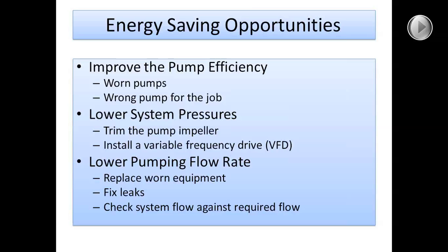One of the major things that we can do is improve the pump efficiency. The pump may be old and getting worn out, and it's just not operating very efficiently. We have tested some pumps that actually had pieces of tarp or something caught in the pump impeller, and that's really cut down on the efficiency. So the pump itself wasn't necessarily worn, but it had some debris in the impeller, and so our calculated efficiencies were low.